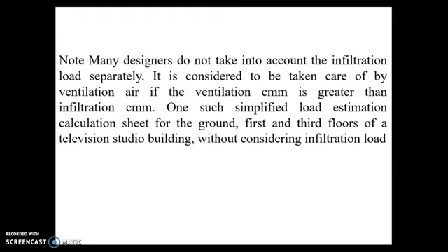They usually consider it to be taken care of by ventilation air, if the ventilation cubic meter per minute is greater than the infiltration cubic meter per minute. Such a simplified load estimation calculation sheet is for the ground, first and third floors of a television studio building without considering the infiltration load. So this is the problem in the cooling load calculation.